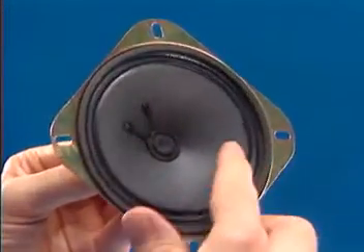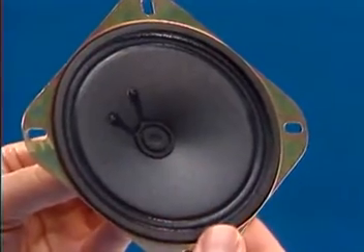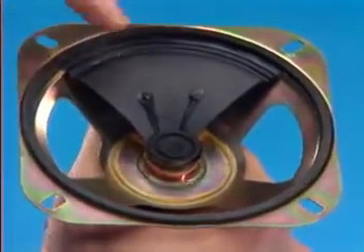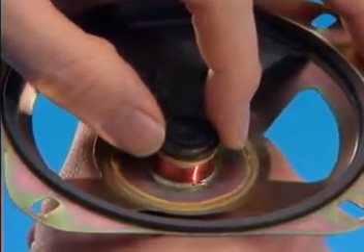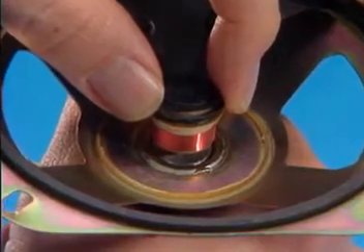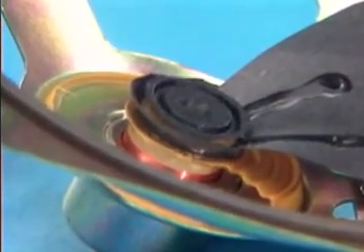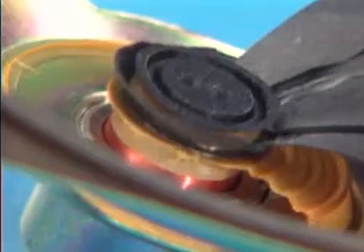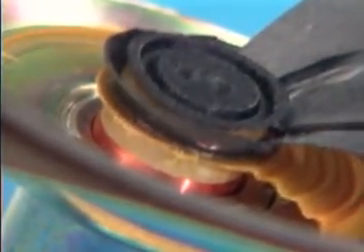Let's look at one more device that depends on the principles of electromagnetism: permanent magnet speakers, which are commonly used in radios, stereos, and TVs. A permanent magnet speaker is made from a paper cone and a permanent magnet. As you can see on this cutaway speaker, the flexible paper cone is attached to a cylinder with a coil of wire around it. One of the poles of the permanent magnet is positioned within the cylindrical coil. When current flows through the coil, it creates a magnetic field that interacts with the magnetic field of the permanent magnet, causing the cone to move in and out. The speaker you are listening to right now uses the principles of magnetism and electromagnetism.